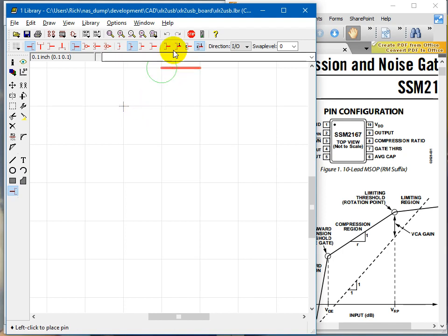All right. And lastly, the visibility. Nothing is visible, which means it's just a pin. I only want the pad, so I won't see much happen here if I only have pad on, because pad is an attribute that only shows up when we go to connecting a fully complete part. In other words, a connection of a schematic symbol and a package or footprint, and pin name only, and both.